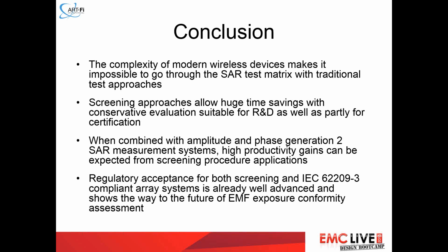How can the user verify that the tested signal is correct? I'm not sure exactly what's behind this question, but there are different ways to do that. One way is to have an external spectrum analyzer, for example, with an antenna plugged into it, and you can see what kind of signal you're measuring. But with our system, we have an embedded function that lets us know the spectrum of the signal, so we can compare it to what's entered in the interface.